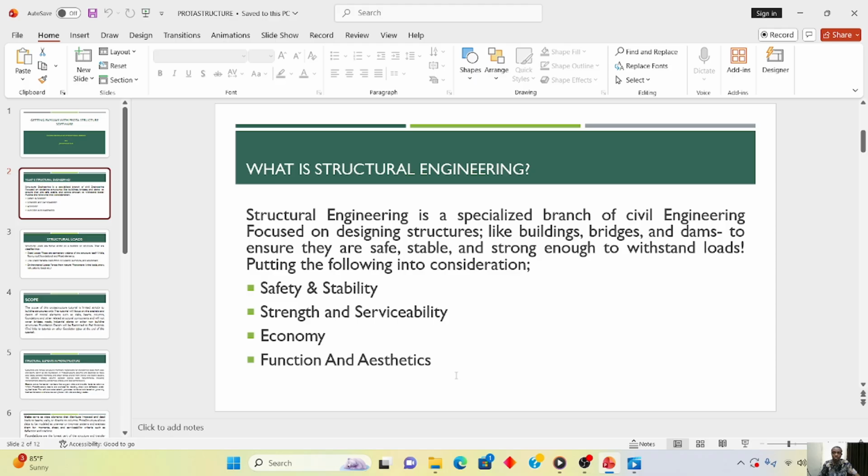In the design, it is recommended that you use a reinforcement bar of 12 mm. Now, during execution, using a reinforcement bar of 10 mm is very, very risky and unprofessional. It shows that safety has not been put in place.